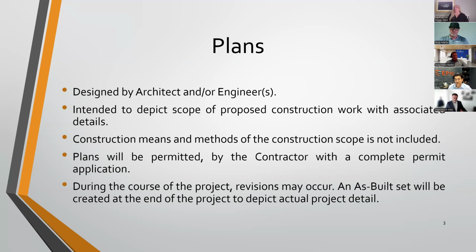And there will absolutely be various iterations of that construction set during the course of it, because especially when dealing with existing structures or existing properties, things are going to get complicated. Believe it or not, the original plans might not be accurate. So while the engineers and architects involved do their best to make sure that's going to take place, things can and will be missed. And at the end of the project, the construction set is going to turn into an as-built set or a record set, which is intended to be the latest and greatest, should show as much detail as possible, and should be a direct reflection of what you see out on site. But again, that's a pretty high bar.